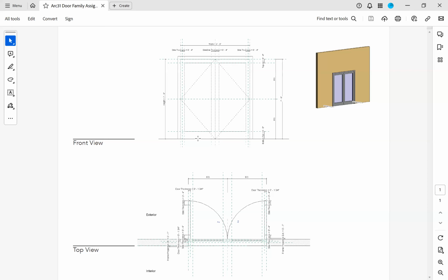That mainly has to do with accessibility. Typically, we have about 10 inches at the bottom minimum, so that someone in a wheelchair can kick the door open if they need to without having to kick the glass. So that's why we have a thicker bottom rail at the bottom here. The verticals, though, are not called rails. The verticals are called stiles. Okay, so when we're talking about the door stiles, we're talking about these vertical frames. When we're talking about the rails, we would have to say the top rail or the bottom rail, but it's referring to the horizontal frames of the door.